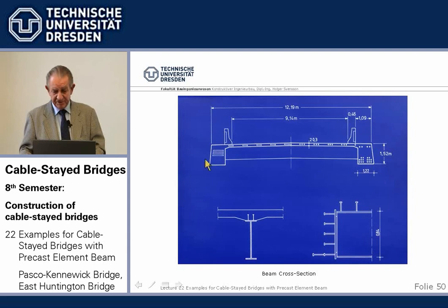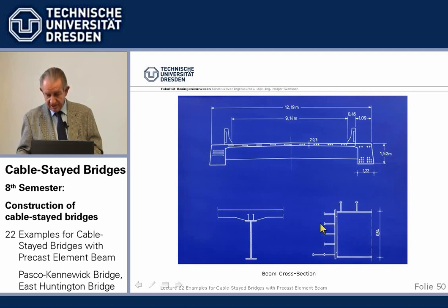Well, that's the cross-section, rather absolute minimum you needed. And here we had then, instead of the steel dowels, we had profiled the concrete to take the shear. We had the steel cross girder like this to save weight, cast at the end the shear studs, of course not the structural steel. The concrete stops here, and the forces are carried by the shear studs.